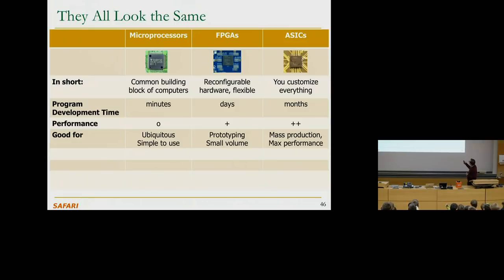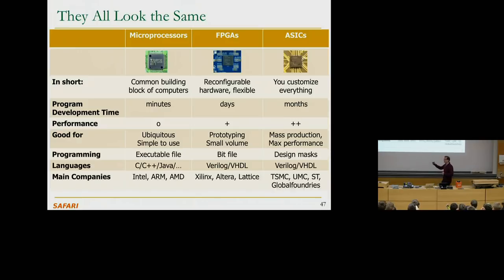And we're not going to touch this because we're not going to build an ASIC in this course. If you're really interested in doing that, you can take an advanced course on VLSI design, for example. Okay, I'm not going to go through this in detail, but let me actually say, basically, languages that you use here are high level. Here we're going to use Verilog, lower level. And this is also programmed with Verilog. People have tried to configure FPGAs with high-level languages for a long time. That's not that easy because doing the compilation from something like Java into RTL, register transfer level, it turns out it's not very easy to make it efficient.